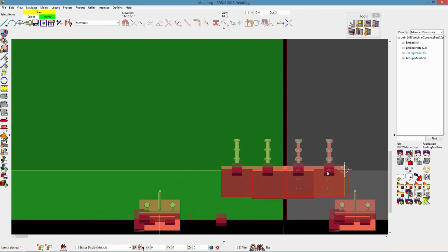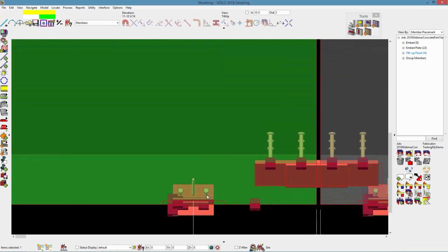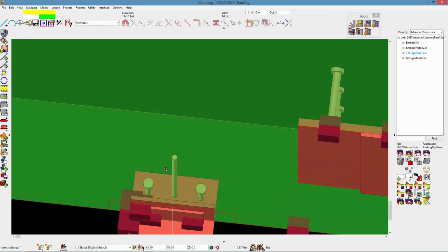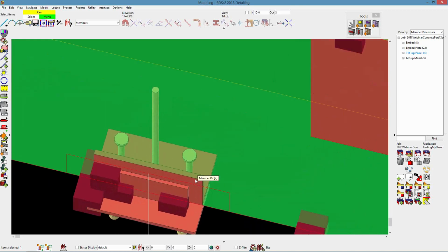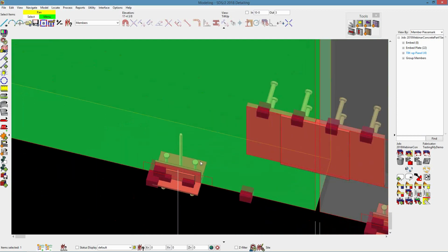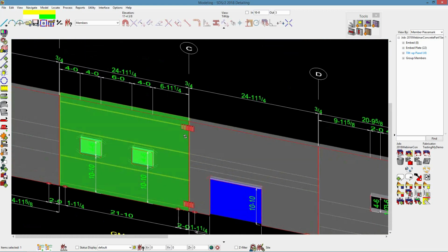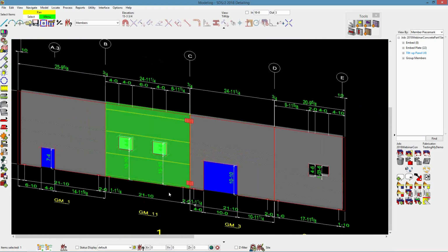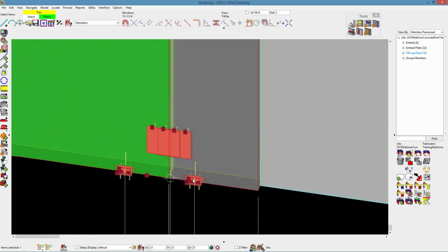I also have a plain plate for welding the two embeds together. You can also see in this view that I have studs and DBAs for the panel embed. So that would be using both the panel to footing and the panel to panel embed assembly. Remember that these are not components; once they're added, they just add in the miscellaneous member for the embeds.